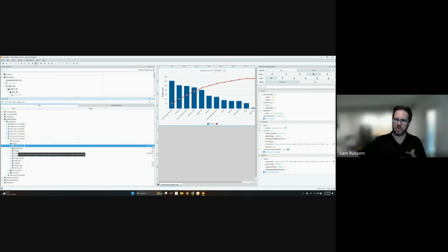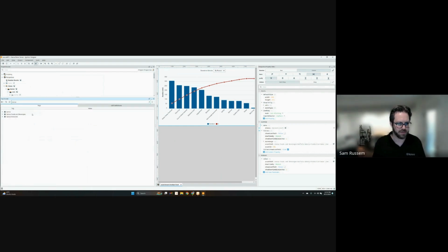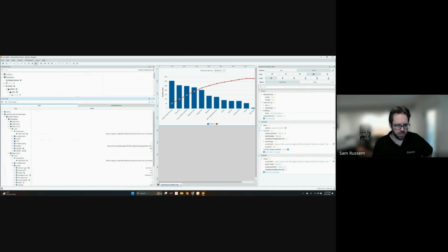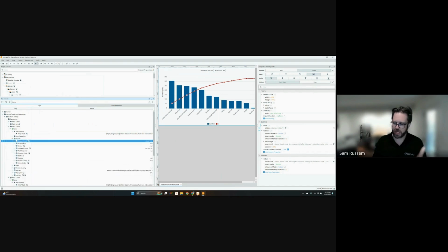You would just be doing reference tags or some other type of derived tag to get to these main pieces of data. I'll come back into these two areas here. So I'm going to point this MQTT path to pack line 3. I'm going to point this MQTT path to pack line 4. And you'll see that we have just these inputs and outputs. Now these are mapped. These are just reference tags that are looking at the right type of data.